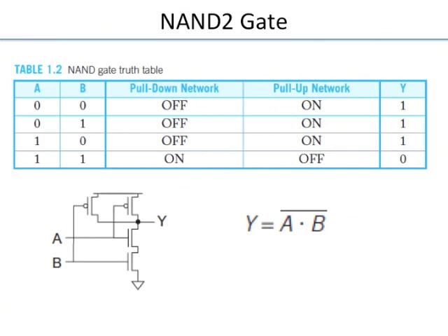Similarly, an output of a gate can be connected to many other gates. So the number of gates it gets connected to is called the fan-out. So that is the definition of fan-in and fan-out. Typically, we cannot say what the fan-out is because it really depends on how you use the gate. But we can say what the fan-in is. Clearly, it's just 2. Fan-out, we don't know. It could be 1, it could be 4, it could be 8, etc.